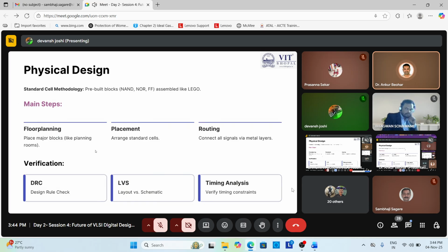where the industry nowadays requires STA experts and has many jobs for them. It checks all timing paths for violations like setup and hold times, without needing any extra test vectors, including calculating delay through logic circuits, for both setup and hold violations, to guarantee the chip operates correctly at a target frequency. All these are very important. In short, it exhaustively checks all possible paths to identify violations like setup and hold timing.